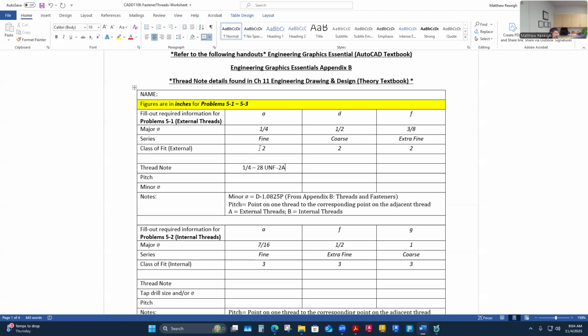That's really only required if you have a left hand thread, because those are odd, which means they're lefty tighty and righty loosey, right? We say standard threads are righty tighty. I spin them clockwise to engage the threads. Maybe you've heard that said, righty tighty, lefty loosey. That's because our standard way of fastening stuff is with a right hand thread, right hand to tighten, left turn to loosen.